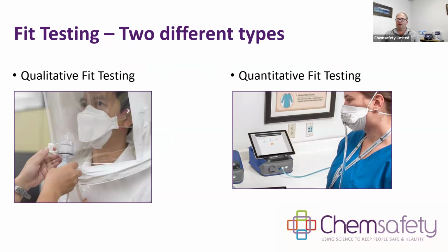So with fit testing, there are two different types. We've got qualitative and quantitative fit testing. Both types of fit testing will do half-face respirators and disposable respirators. But once you're getting to full face or beyond, then we need to be talking about the quantitative only.